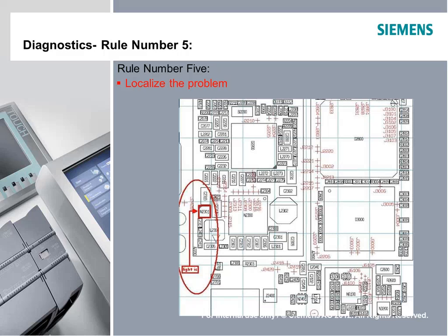Once again, talk to the people on the floor, and maybe it's a problem with, for example, a temperature controller. This tank is going awry. So maybe we just focus on a temperature PID loop on a tank, so we can pretty much ignore everything else in the system and focus in on a localized problem.